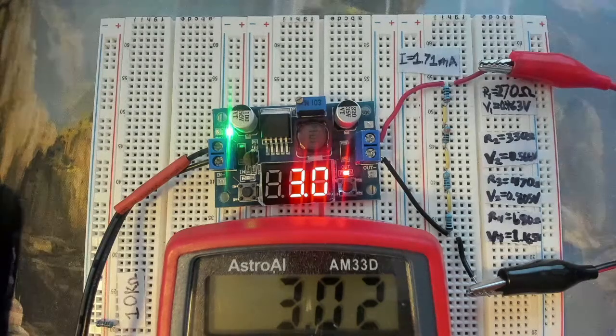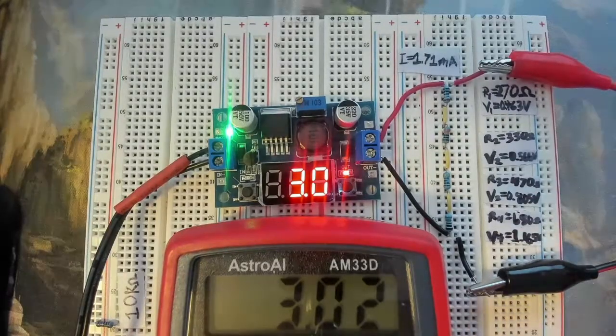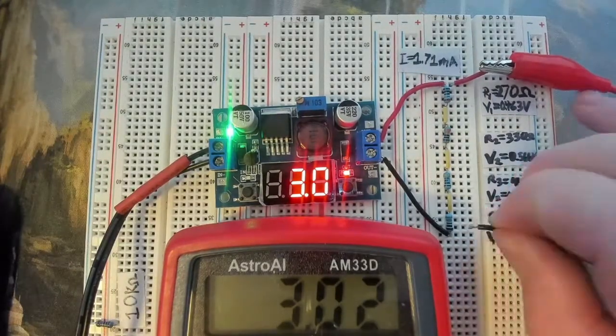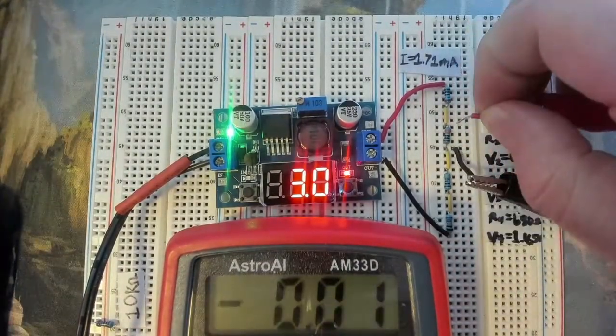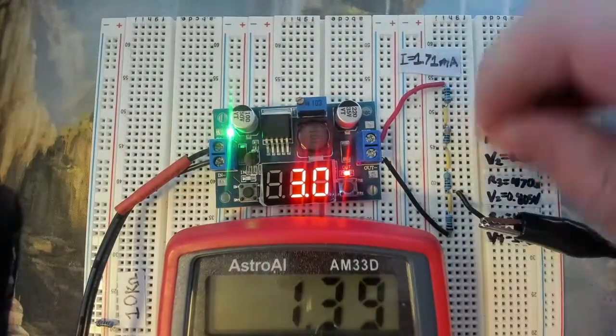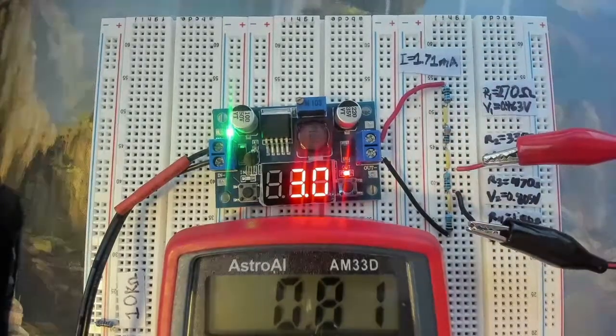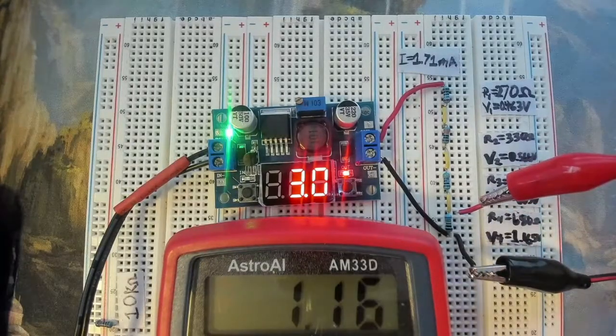Alright, so I hooked up our circuit with each of the values that we calculated. And what we're going to try and do is measure how close we can get. Now you'll notice that the power supply I'm using is a little bit off from what I'm measuring, so that might affect our measurement a little bit. So what we're going to do is measure the voltage across each resistor. So this is pretty close to what we calculated. That's also pretty close to what we calculated for the 330 ohm resistor. For our 3, we're basically within rounding error. And we're also pretty close for our 4.